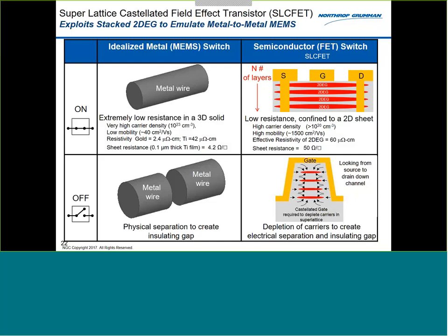So here is a question of whether we do an RF analysis, and in particular skin depth. We really haven't looked at what the skin depth limit is. Of course, I don't show any dimensions on here at all, but these castellations are on the nanometer scale. So where we would be limited by skin depth would be a relatively high frequency. I think we'd have to go certainly into the tens of terahertz range before that would matter, but that would certainly be a potential limit at some point.